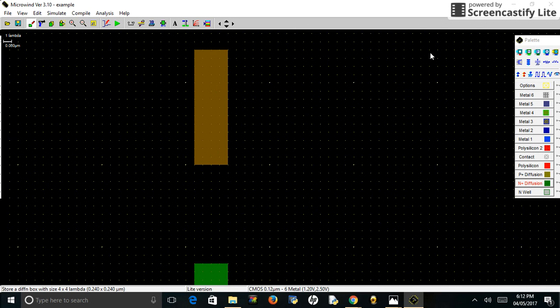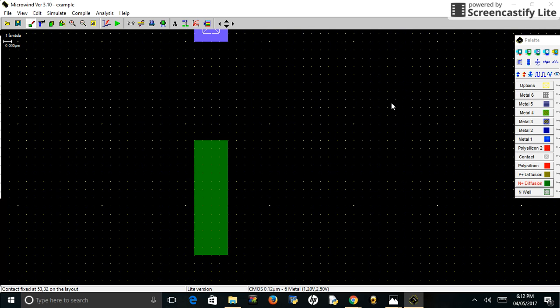This is PMOS, so we require P plus contact. This is the P plus contact. Just click on this. This becomes the source. Now again for the N type NMOS, this becomes the N contact, and that's the drain of the NMOS. This becomes the source.